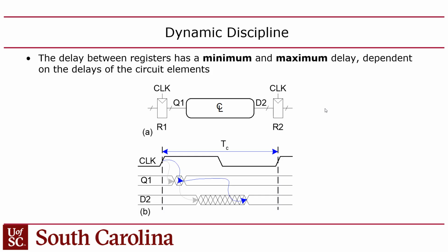That's one of the big challenges of digital design, that difference in abstraction between when the problem happens and the way that you have to fix it. You're fixing it at one abstraction level, but the problem is happening at another. The problem is at the gate level, but you have to fix it at the HDL level. So it's tough.